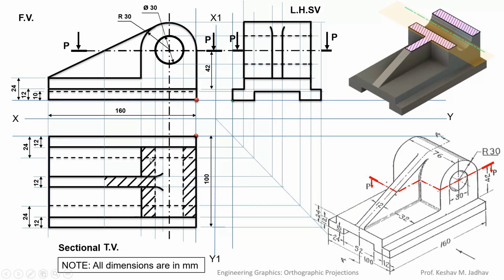So upper part of this rib we have cut and thrown away. So this part of rib will not be present now. We have to erase this rib portion and we have to remove this dashed line in the hatching part. So it will be like this. Now another rule for hatching line is outer edges of the hatching line are always continuous thick lines.